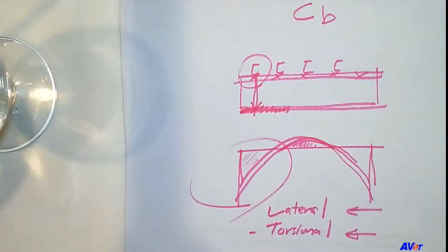And that is why, ladies and gentlemen, when you have a simple beam with the concrete floor on top of it, and somehow you connect your concrete floor to the top flange of the beam, which is the compression flange because it's a simple beam, right? Your beam will be fully braced because the compression flange cannot move. And in that case, you will easily reach MP.